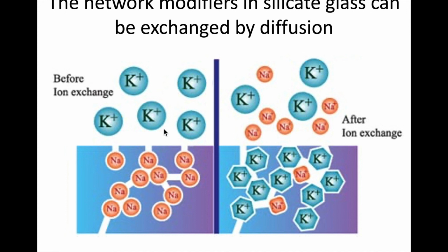And so this continues to happen the more that it's in the ion exchange bath, right? So you kind of know the relationship between diffusion and time, but also temperature. Think about how temperature affects it, the higher temperature, the lower temperature, and what effect that has, and where it diffuses, right? So it starts on the surface, but it gradually works its way into the interior. So it's a diffusion process, but I want to point out that it is charged species, so there is an aspect to this that you have to account for that charge.